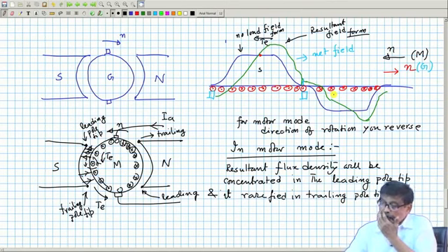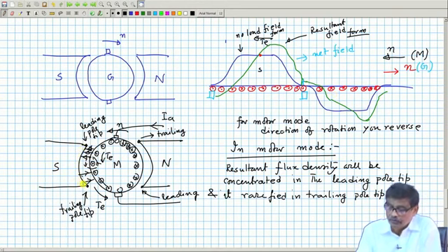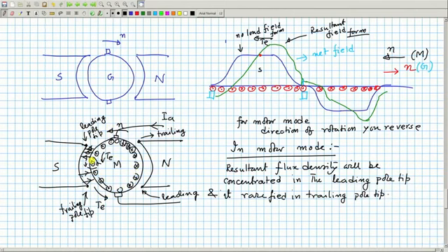Okay. Now therefore, the compensating winding will be here, and it depends upon the arc of the pole divided by this pole pitch. This ratio will decide how much of this armature conductor MMF can be nullified by that. This will never be able to nullify this flux in the q axis, because this will remain unattended.